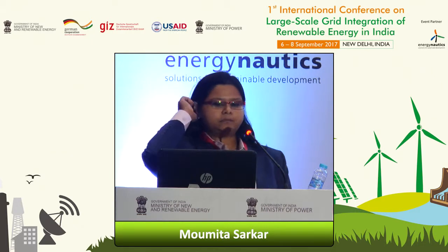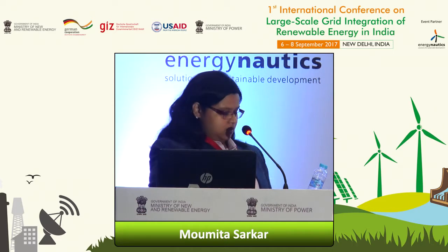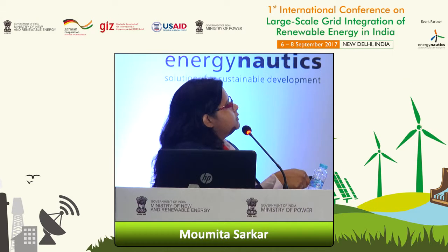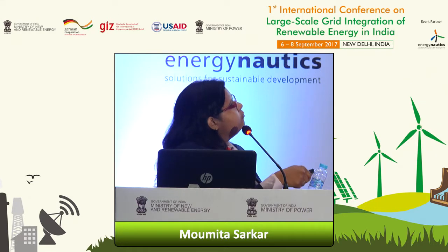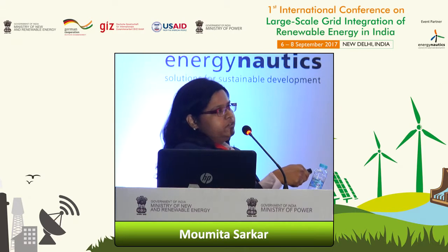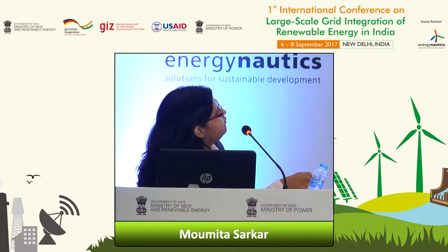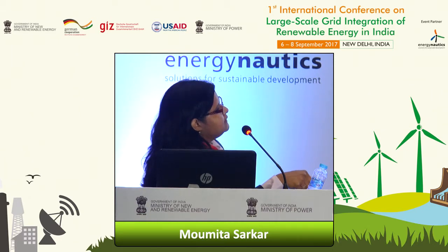Next, to do the voltage stability studies, we incorporated the wind turbine model in an aggregated form into this test system. This is an academic system developed at the Technical University of Denmark, mainly for voltage stability studies. It has 4 central power plants, and with this system, a wind power plant of 300 megawatts has been added at this end, and it is connected to the system through this long